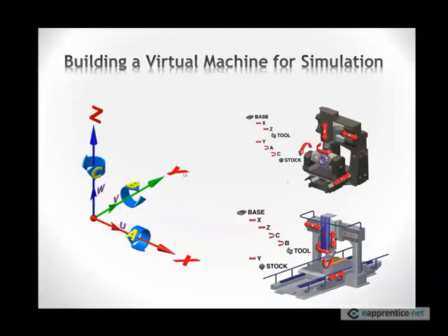This is an industry standard, but like any standard, everybody abides by it a little bit differently. You can change, for example, the A-axis rotary direction. Even the way you mount rotaries, A could be around B, around the Y-axis on some machines.